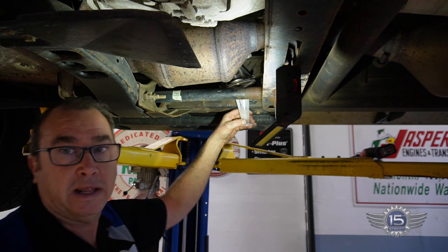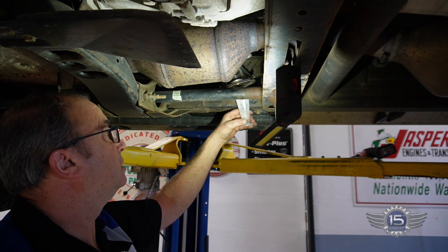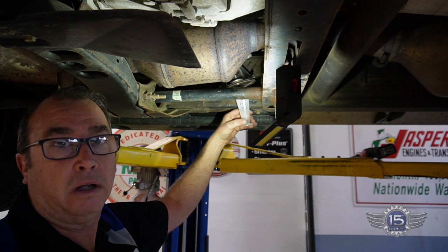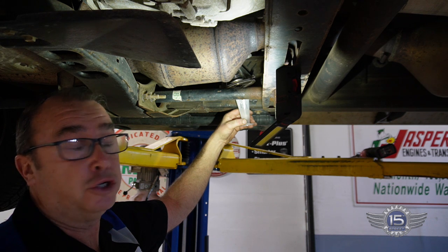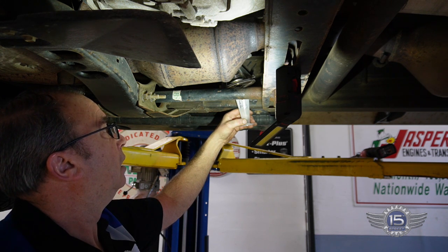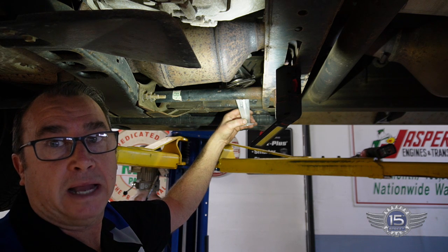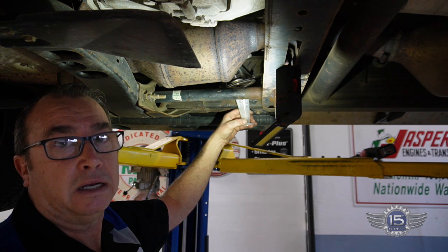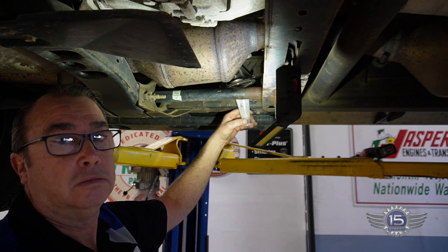We've already proven that our NOx sensor isn't doing what it's supposed to be doing, so as soon as this test is over, we're going to put us all back together, and we're going to sell the guy a NOx sensor number 2. I will put that in, show you how I put that in, and then we'll take it back out on a road test again and ensure that it goes to 0 like it should.